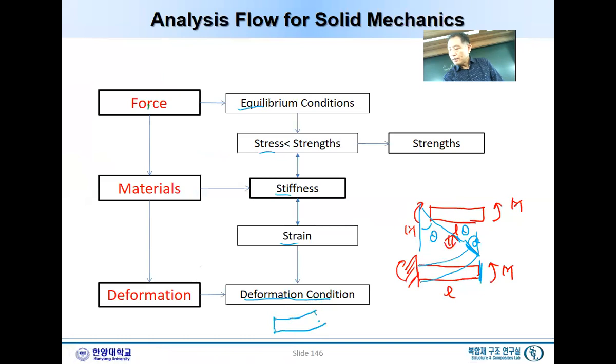It goes like this, theta, and I will put this deformation into equations, and what equation will show us this kind of deformation. Once we have the deformations, strain can always be easily given in terms of deformations. And once we have a strain, we can always get a stress by considering stiffness.